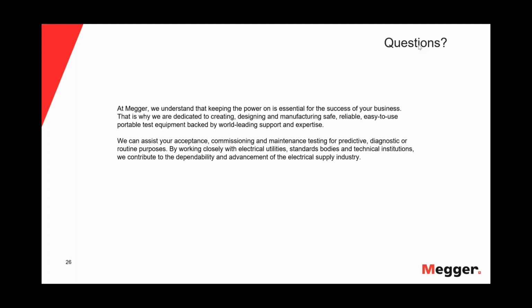There was a big discussion in IEEE about this topic many years ago, and there is a very good write-up in the IEEE 400.3, which is a partial discharge field test guide, about water trees and the relation to being able to use PD to detect water trees. It's not possible, okay? Because from the physics point of view, you need a gas discharge, and to get the gas discharge, you need a high resistance, and you don't have a high resistance with water.